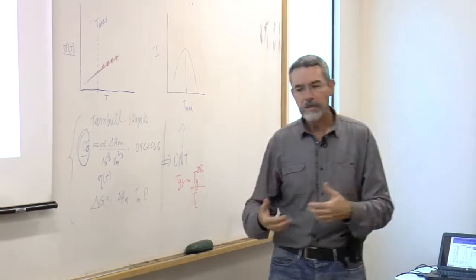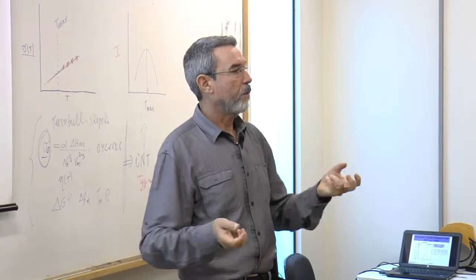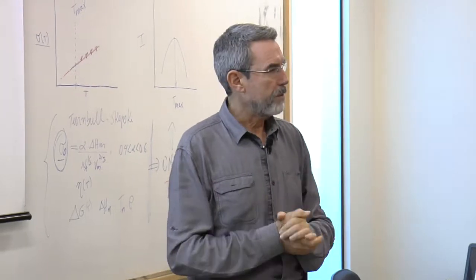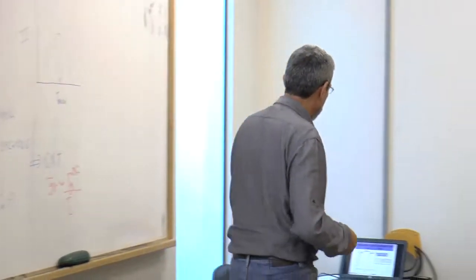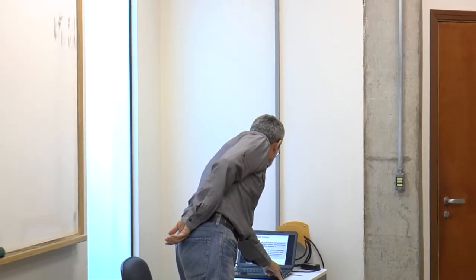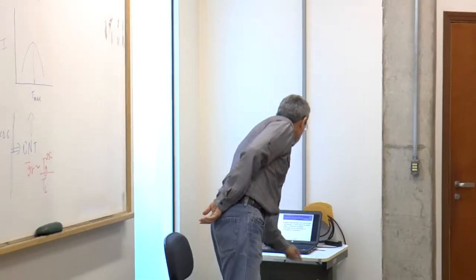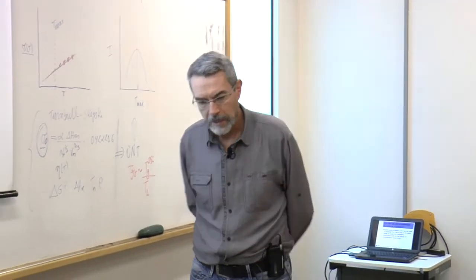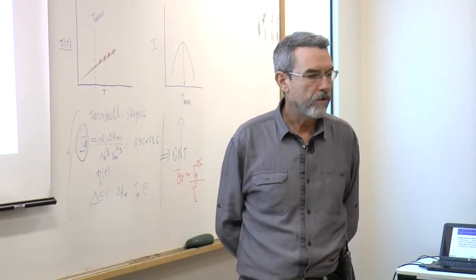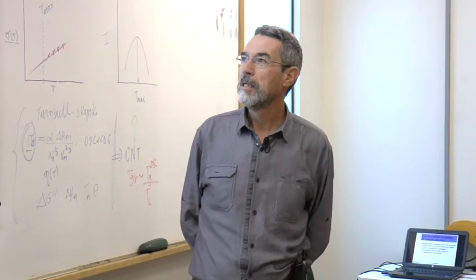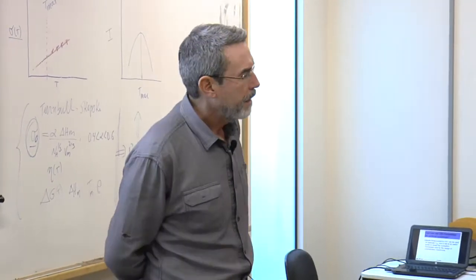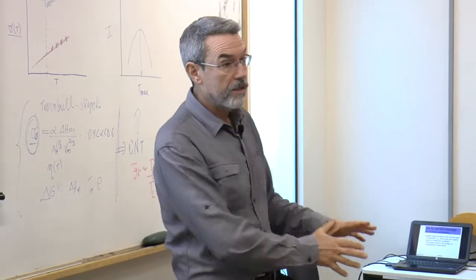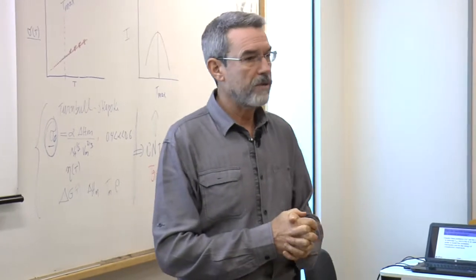Understand the reason why certain glasses crystallize so fast, or certain materials crystallize so fast, while others are very reluctant to crystallization. We have also done similar experiments for B2O3, and the same explanation applies for B2O3 and other reluctant glass formers. So the theory can be used to design experiments or to design materials that are reluctant to crystallization. Sometimes you want materials that are very reluctant to crystallization.